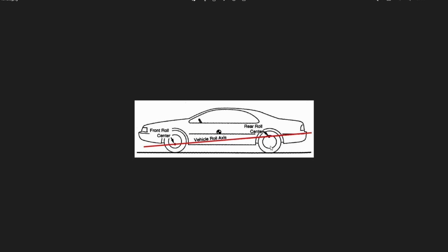The rear, low roll center, so softer. As the front bites into the corner, the rear doesn't have a lot of initial grip. But then mid-corner, as you get into the corner, the rear tires are still more evenly loaded. So mid-corner, the rear has good traction. So you go in aggressive, the rear doesn't respond that much. Mid-corner, the rear grips well. You get on power, the front responds quickly with a high roll center. But the rear doesn't have enough initial grip to stop a slide or straighten out. So when you get on power and accelerate, the rear is wanting to fishtail.